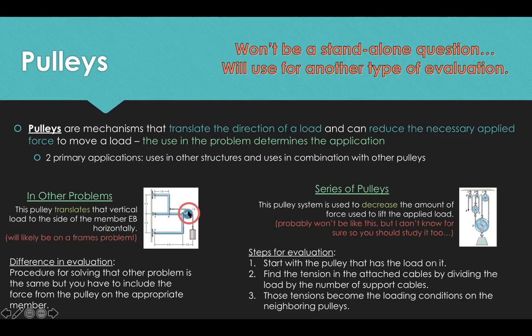So again, that would mean the reaction forces at this pin, but alternatively, you have to make sure you're drawing this force on this member, on EB. Which is why EB is not a 2-force member: it has the reactions at these pins, but also this additional force on it. So that's not a 2-force member. Any questions on what I just talked about?